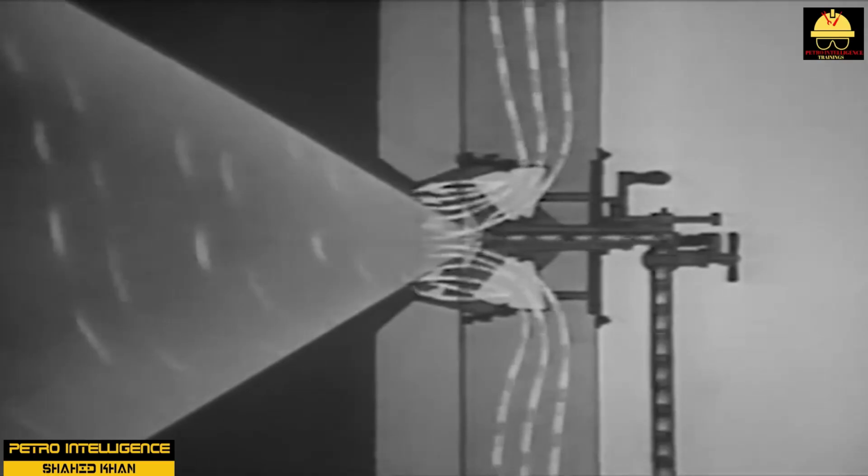Low-NOx burners are designed to be operated with lower amounts of excess air than typical burners. The use of tertiary air registers reduces nitrogen oxides in the flue gas stream. The burner uses a small amount of steam to better disperse the fuel and oxygen.